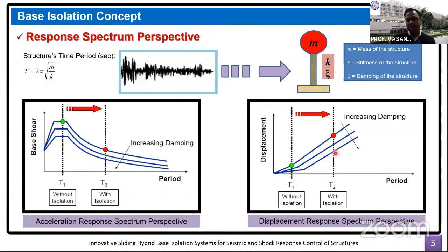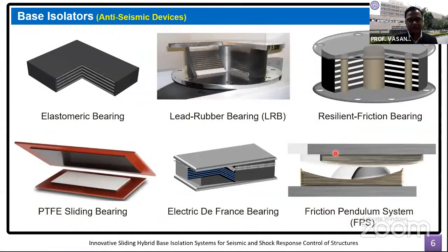Typically, steel structures exhibit damping of around 2% of critical, whereas reinforced concrete structures exhibit damping of around 4 to 5%, depending on how extensively it is cracked. If it is more cracked, then the damping experienced is in the range of about 5% of critical. Whereas the damping of the isolation system is in the range of 10% or more, particularly when it comes to elastomeric bearings.